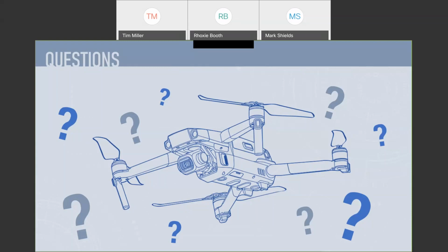And for weather limitations, does rain mean you can't fly that day? What are the weather limitations there? Again, it depends on the drone. There are waterproof drones out there that are pretty affordable, so you actually can fly in a full downpour. Really, you need to worry mainly about wind conditions. If the wind is blowing over 25, 35 miles per hour, you're going to have a problem.